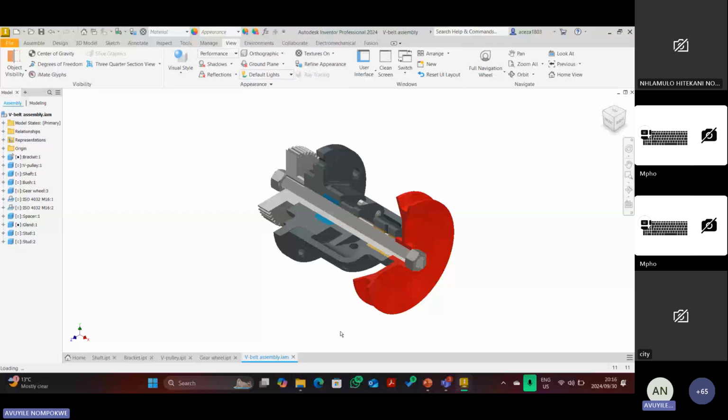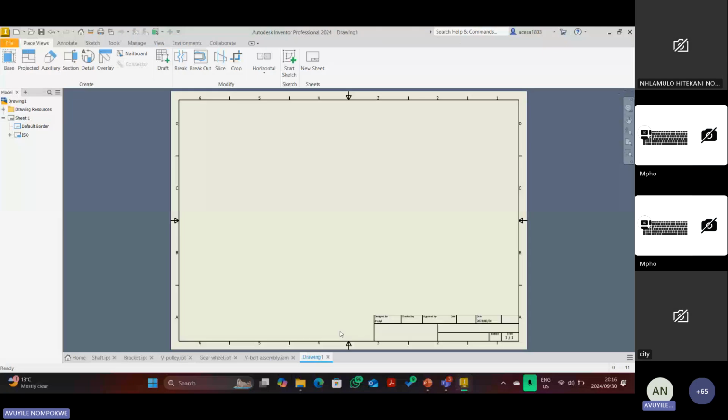What you need to know is that you just need a plane that will be tangent to your surface, right? So how do you get that? You just need a point on your original sketch, and then you go to 3D model, plane, and then tangent to a surface through a point, and then you're good to go.